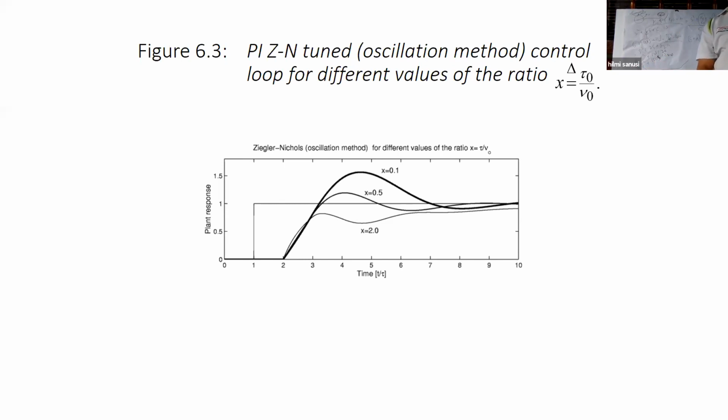So Ziegler-Nichols, we give a step response and observe. So this is the ultimate cycle. This method is used when the system model cannot be obtained, or is difficult to obtain, either as a differential equation or transfer function. So Ziegler-Nichols is really a black box.